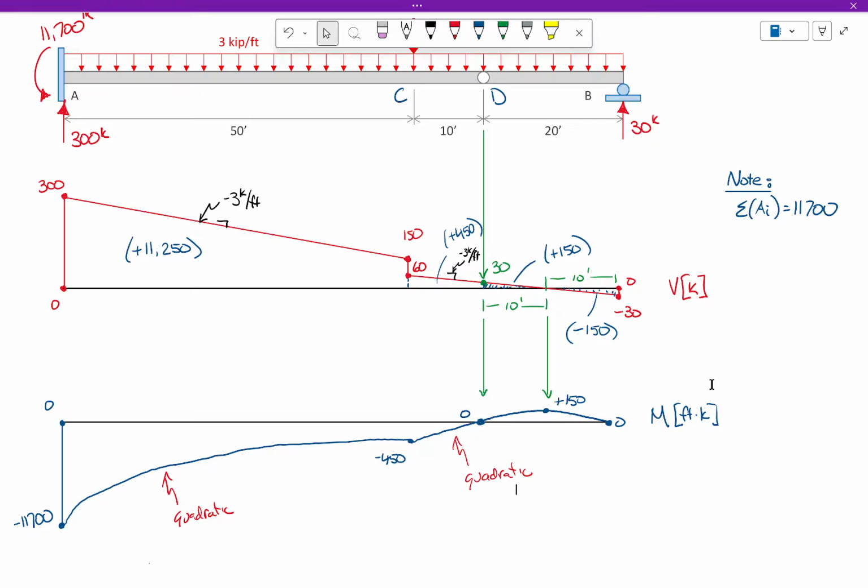Okay? If anything, I'm really encouraging you to do it this way because if you compute the correct reactions and you ignore the presence of the hinge when constructing the moment diagram, it will serve as a check that those reactions are correct. Because you're drawing the moment diagram and it should cross 0 right there. That's sort of what I'm getting at. Like, ignore it and see if the answer works out the way that it should. Does that make sense? Any questions?